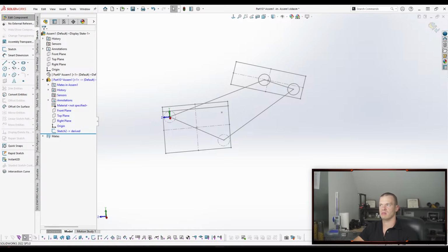I used to design top down, where I would click on edges and stuff like that and convert entities into the parts, and that works, but it's just not as stable, right? Features break as you keep doing more and more stuff. And I know that master modeling is one way of eliminating that. I just am not familiar enough with it to say you should use one over the other.